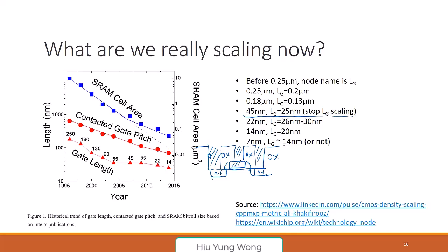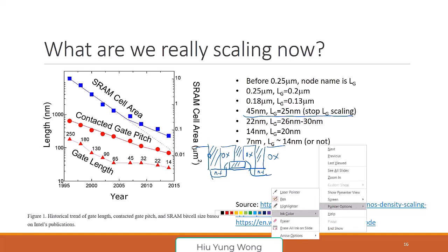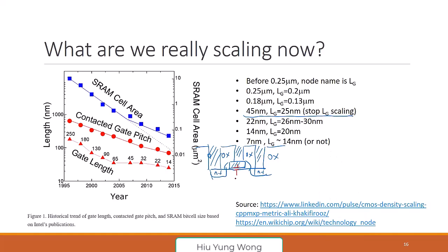This is a metal. So what capacitors do you see? I have a capacitor. This is the C-ox, which we cared about a lot in the past for scaling. But there are other capacitances. These are the so-called parasitic capacitors. You will have capacitance to other places. Nowadays, C-ox is no longer dominating.